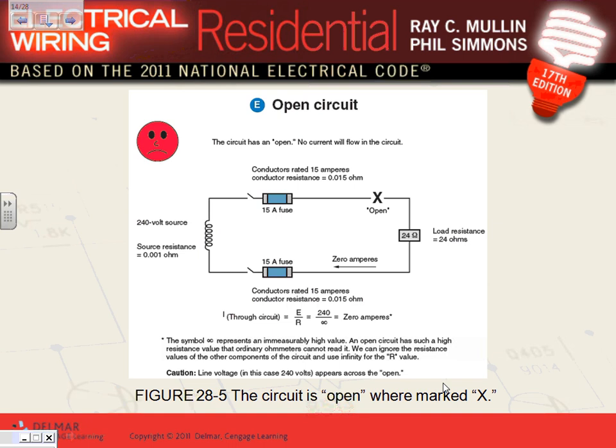So open circuit. Now who's the troublesome one? Jackson, my friend, went to a wire nut sitting like this. That's supposed to tie the circuit, the motor lead hot to the lead coming from the service, tied with a wire nut. He unscrewed that wire nut, right? And you open this circuit. So what's going to happen, guys, to a motor like this if you open the conductor? Nothing. This machine is off. This is in a single-phase system. In a three-phase system, open circuit is bad news.